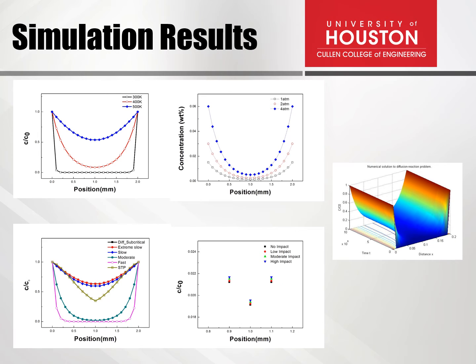So here we have the results after aging for selected time spans. First of all, we would like to check the temperature effect. We can see from the diffusion rate expression that with increased temperatures, diffusion will accelerate and diffusant accumulation can be observed in the diagram. However, reactions also strongly depend on the temperatures. There is competition between the accelerated ingression and the consumption of diffusant.